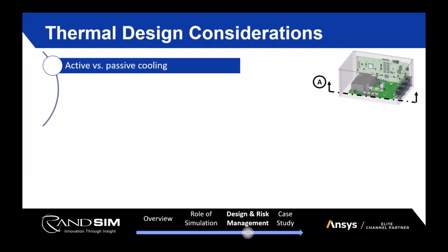The big thing with thermal design is, are we looking at active or passive cooling? And if it is active cooling, is it air cooling or some sort of liquid cooling form? And while there are some general rules of thumb for when you should look towards each of these, it's not very cut and dry. Analytically speaking, there aren't a lot of solid relationships that can give you a solid answer of, yes, passive cooling is going to be sufficient.